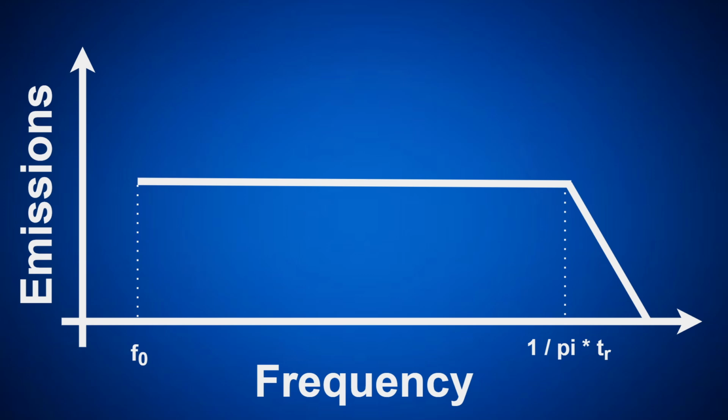well, you actually have a similar one with the common mode noise, except it's even better in this case because we don't have a quadratic relationship between the frequency of the signal and the strength of the magnetic field that it generates. So in this case, we actually start out with a leveled off emissions envelope, and then at that breakpoint, it will start to decrease significantly. And of course, one of my favorite obvious strategies we can use to reduce our common mode emissions is, again, to just reduce the operating frequencies of our electronic circuits.